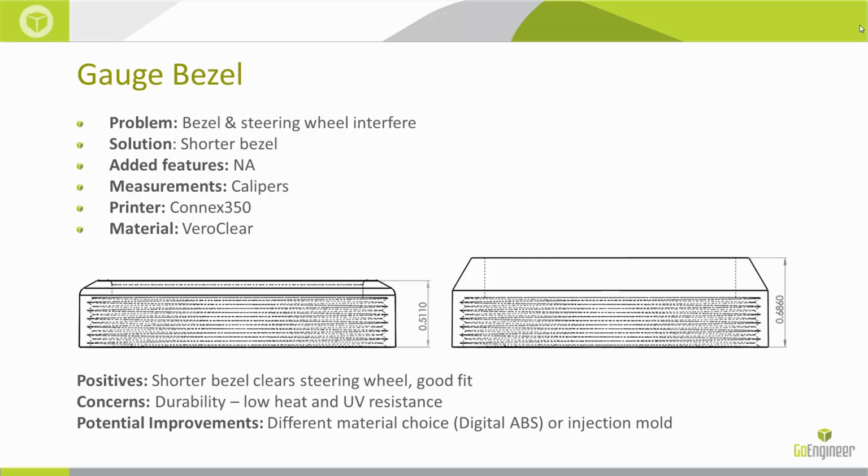The downside of using the PolyJet part is that they're not as durable as the FDM thermoplastics. Ideally, I would be using an ABS or a nylon or a black Ultem for its heat resistance, and even ASA now for its UV resistance. But I used the PolyJet for the threads, which means I'm probably going to have some issues come summertime if this is in the heat, and over time, UV resistance. I've left it uncoated. I could paint it and give it some more UV resistance.